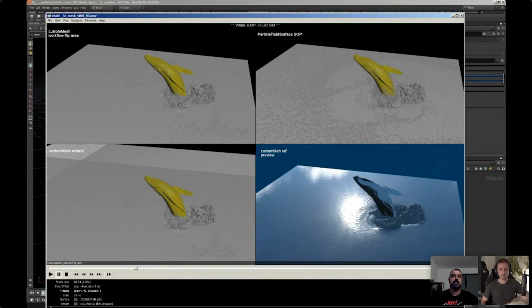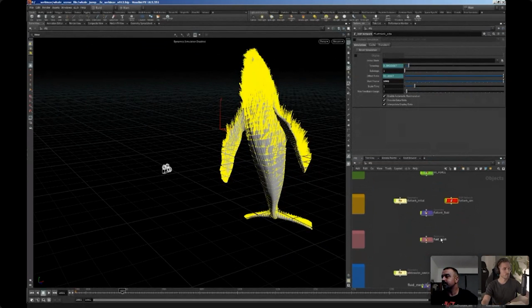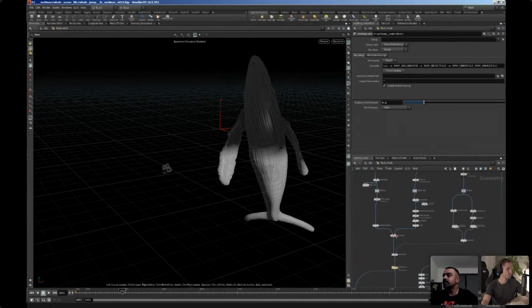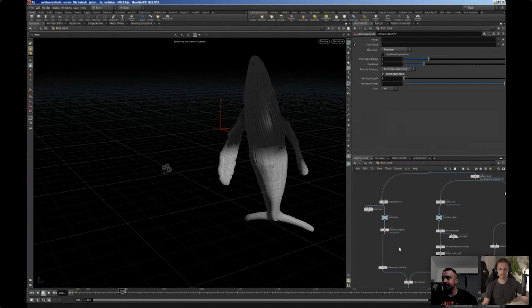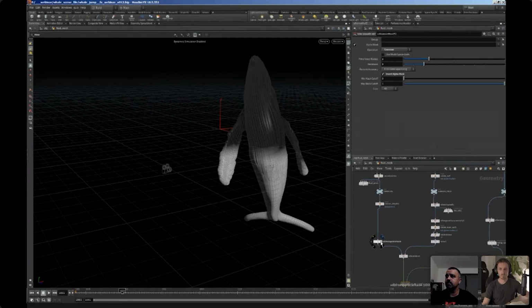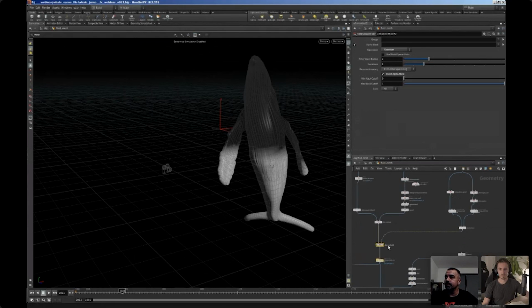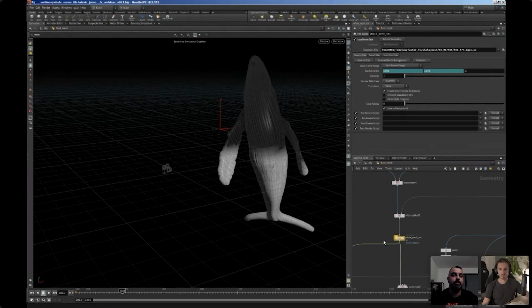And the thing is that you can cache every step. With the particle fluid surface, you need to wait for it to do everything. You can go inside and cache the steps, but in my case you can split some parts. So for example, if we go inside of Houdini, this is the part where we do the VDB operation: first extracting the particles converted to VDB, then the surface field, combined with some masking, and then we can write this VDB as a base thing.